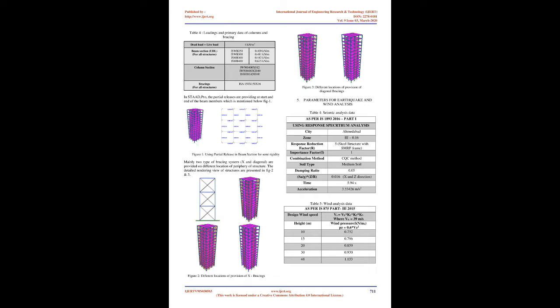2. Literature review. Nandisha and Kashinath, 2017, investigated the analysis of a multi-story steel space frame by varying the fixity factor and found the strength capacity of joints, and performed linear static analysis of a semi-rigid connection steel frame using the response spectrum method. Considering a fixity factor of 0 for pinned or hinged joints and 1 for rigid joints, the variation of bending moment and shear force with varying fixity factor was found out.